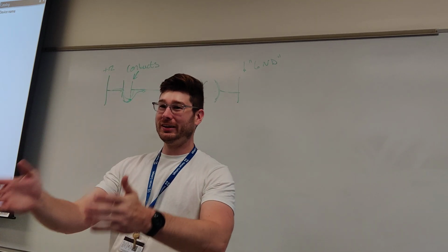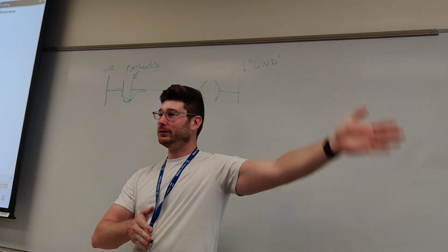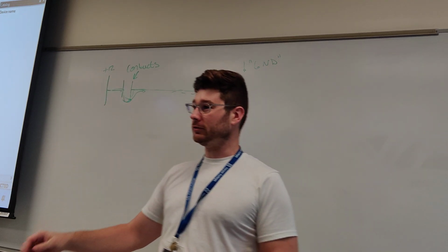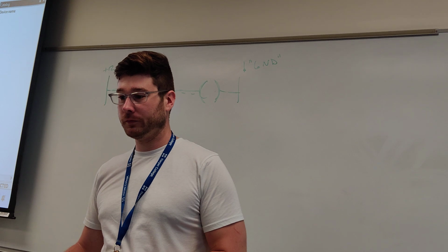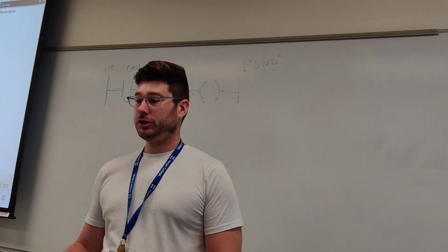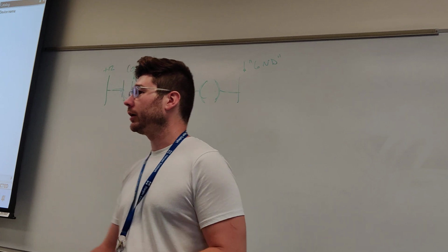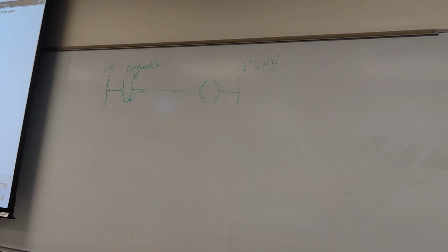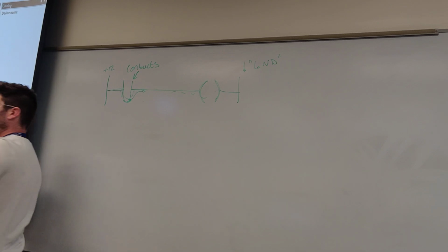It's our input on the left side. Always inputs on the left, outputs on the right, contacts and coils. Good vocabulary to refresh on. Here is where we put our LED, LED-G, or you can pick it out of the list. So now what we can simulate in our heads is if we were to press this button, we would bridge the electricity from this side over to this side and turn on this element, which would be our green LED.